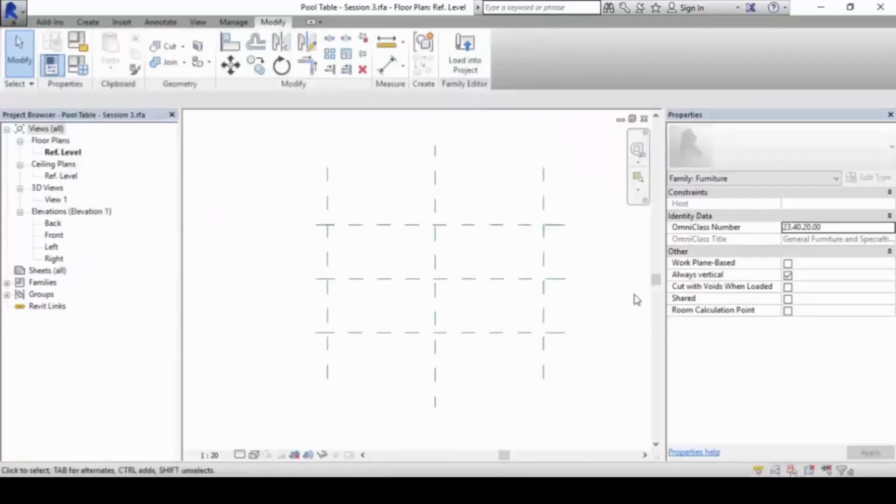Okay. Next, we want to set up the machine. We want to set up so that we can flex them, set up the parametric qualities of it first. So we are going to do so by adding in a line dimension. The first thing we do is we want to make sure the model, when flexing, does not expand or contract all over the place. We want it to be pinned down or nailed down so that it will only grow or shrink within the same axis here, within this location.